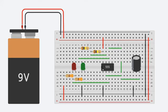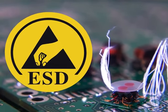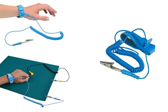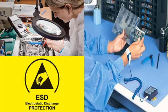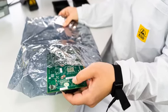Since ICs are very sensitive to static electricity, they should be handled in accordance with electrostatic discharge, or ESD, techniques. When we touch them directly with our hands, they can deteriorate quickly due to the static electricity in our body. This electric discharge can cause damage to electrical tools and components, and, in some cases, actually cause equipment failures. The most frequently occurring damage caused by electrostatic discharge is when a person or tool that is electrically charged touches a grounded device which has a low resistance to static electricity, which in turn causes the sudden flow of electricity between the two objects.